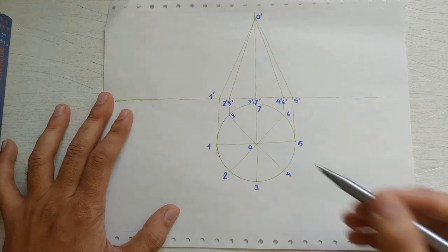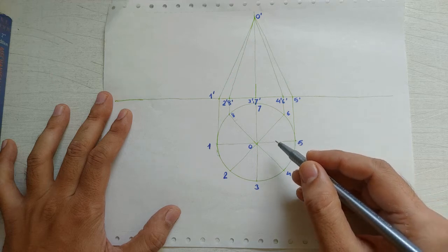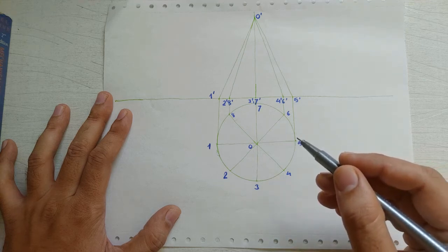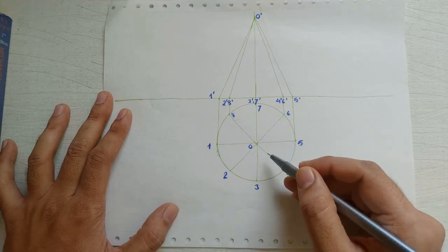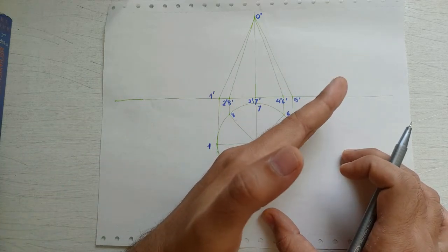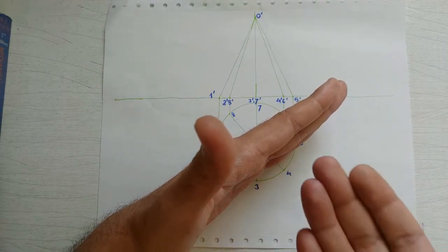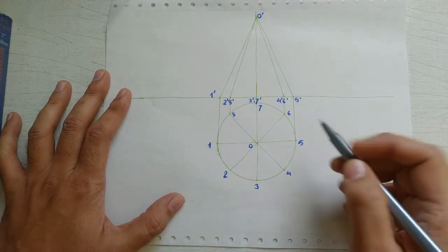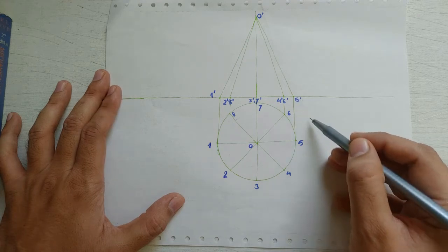So the cutting plane we have to introduce as it is 10 mm in front of the axis and perpendicular to HP and inclined at 45 degree to VP. As I told you, it will be visible as a line in top view because the cutting plane is like this. Okay, it is inclined to VP and perpendicular to HP, right? So now, but where to draw it? Obviously we have to draw a line of 45 degree to XY because the angle with VP is 45.